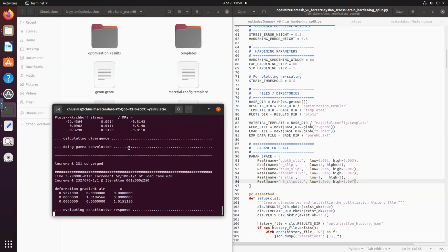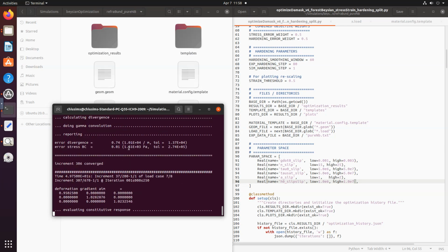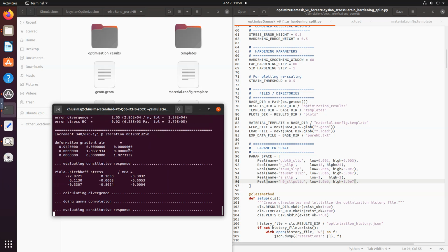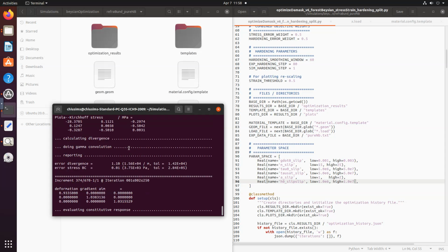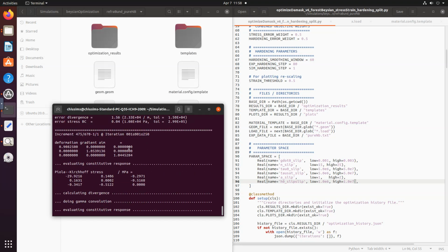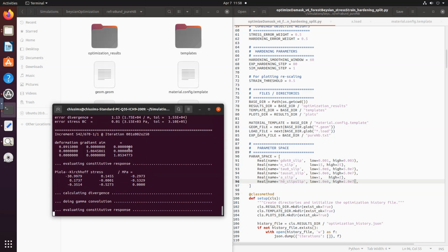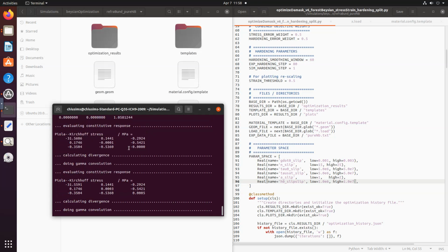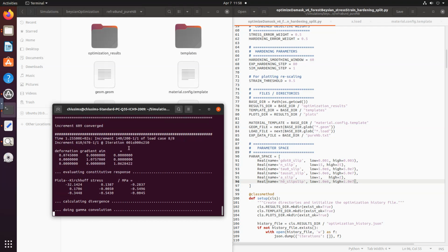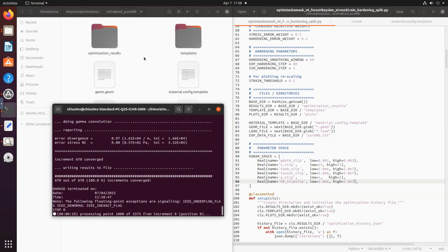So the idea is you run the optimization scheme in a very close window and let it find its parameters, right? So the best idea will be to identify some parameters that are available in literature for a similar material, use that as a relative idea of which would be my parameter space, use them here with a lower window and an upper window, and then let the optimization run and find its results.